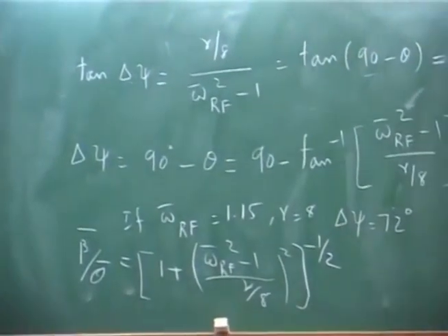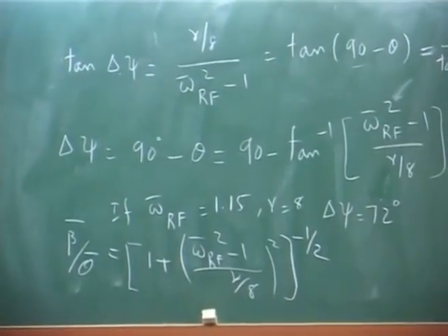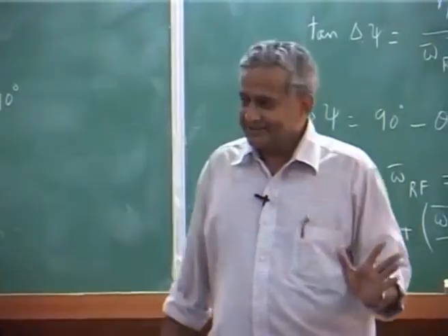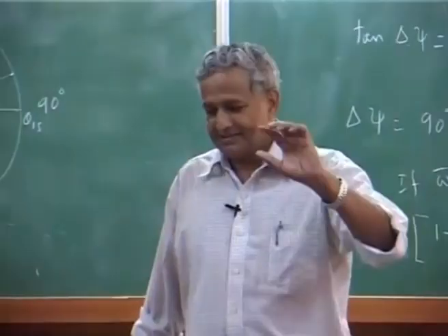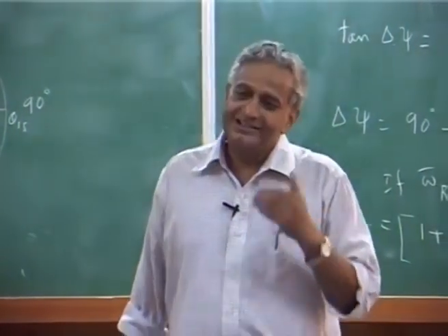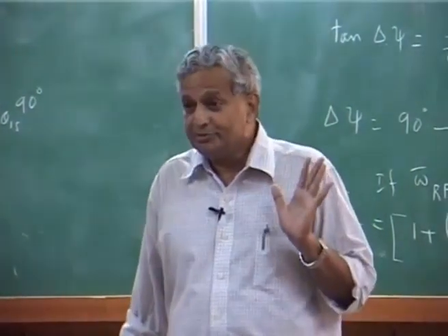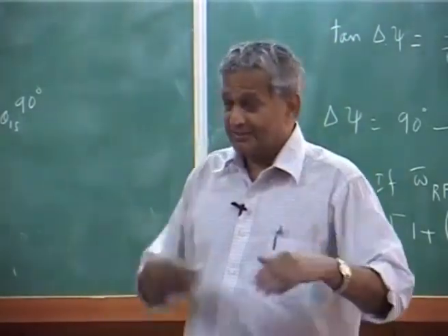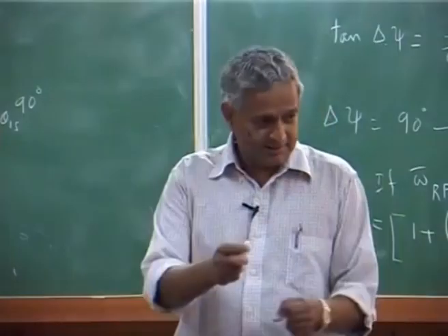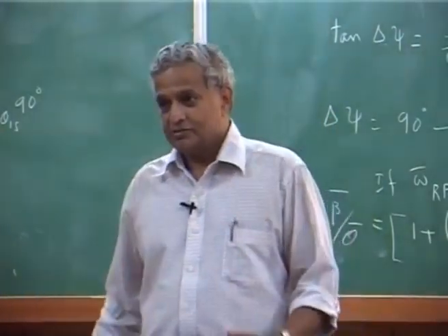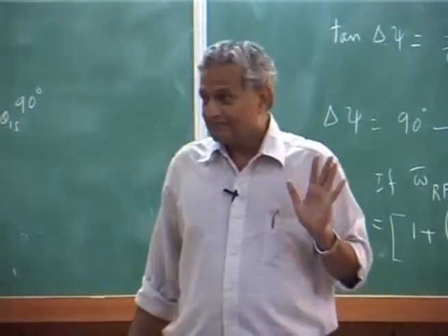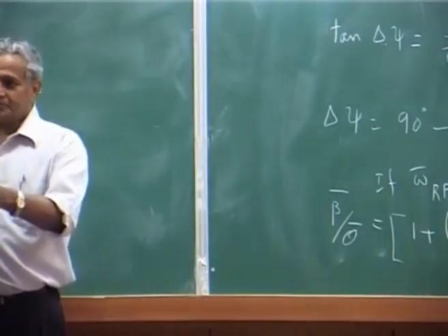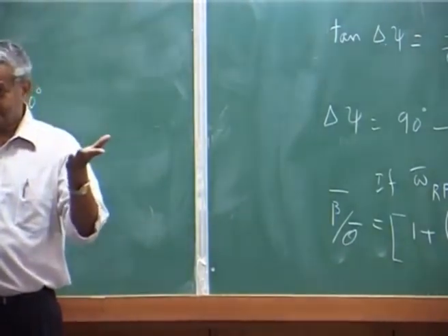No, it may vary with forward speed, okay. But control rigging is done for one, that variation is not very large, that is why it is done at one value and then just left. After that, pilot has to fly. If there is a coupling in some other forward speed, then he has to adjust. So, the flying he goes through a training. So, the key aspect is coupling between longitudinal and lateral.